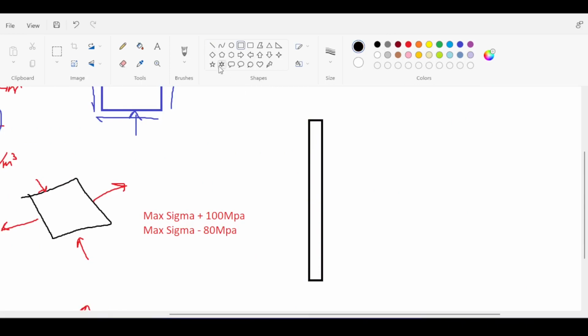tested on a steel rod under an axial force in both directions. There were no forces on the lateral directions. On the lateral directions, there were absolutely no forces. You had only a uniaxial test. Now, this is contrary to what you see in the material, because in the material, you have sigma x and you have sigma y. So the F yield you get from the test is actually not going to be sufficient to deal with this, because this is a biaxial state of stress.